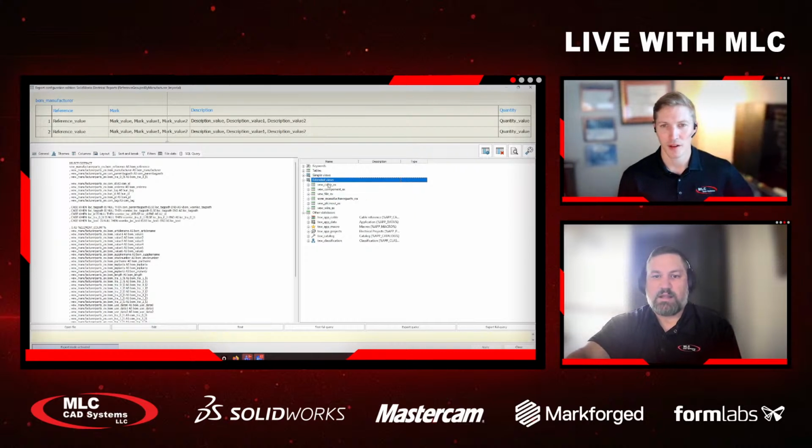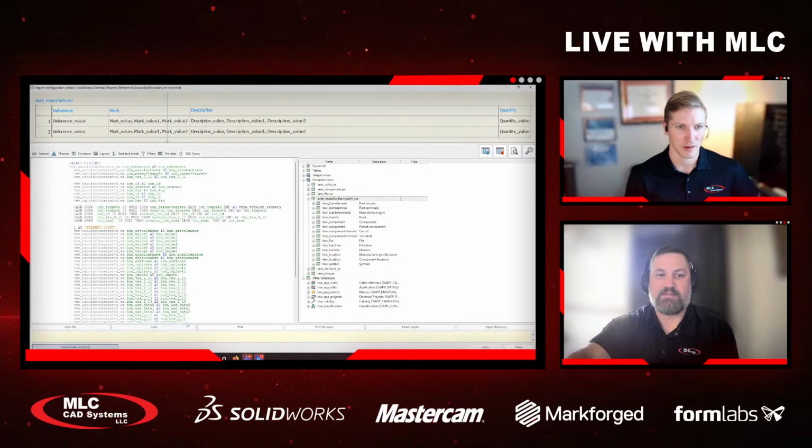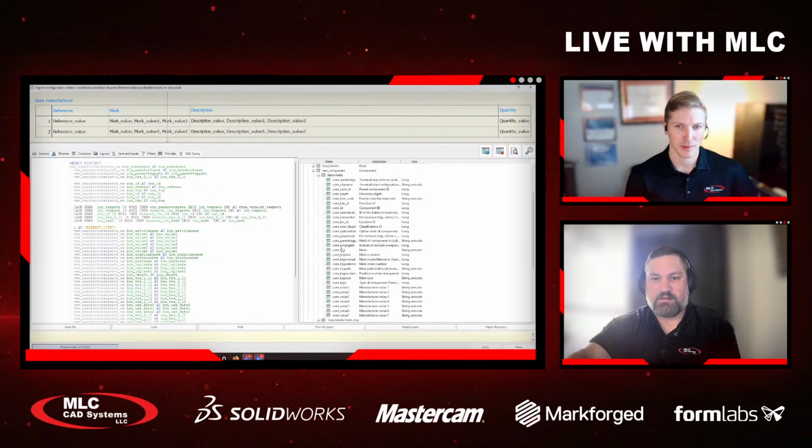And if I were to expand anything that's in this bolded group, you can add into this report as necessary. Now, I don't want to get too deep into that. We already have all the information that we need, and you can actually see the join statement over here. If you hit edit, it even looks like SQL. So if there's something that you need that's not part of the original statement, then you can come in here and find something. Maybe you want to find the terminal strip that it's located on or its location ID. All you got to do is double click this and it will also add into this query.